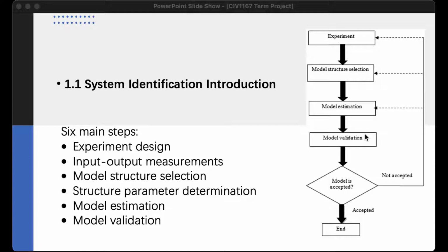The gray box model assumes that part of the information about the underlying dynamics or some of the physical parameters are known and the model parameters have some constraints. The user-defined model assumes that the commonly used parametric models cannot represent the model it wants to estimate. It can define a special system model by using a template with a predefined input-output interface.